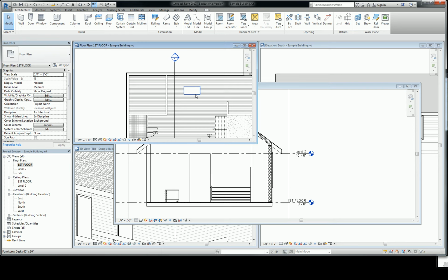Contractors will take your BIM model and modify it, because they don't do it the same way we do, but they'll do a quantity takeoff and build a schedule of all your walls. So the key is, rather than modeling the insulation itself, can you get the same information a different way? For instance, taking all of your exterior wall types and calculating the square footage of that core. Does that make sense?